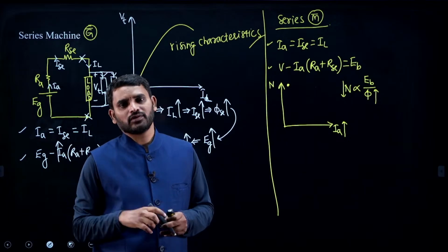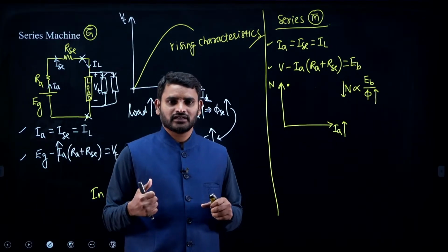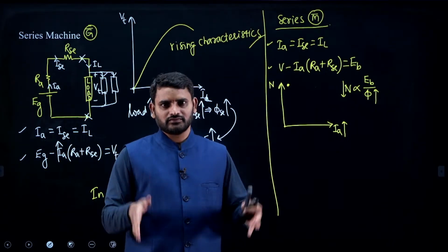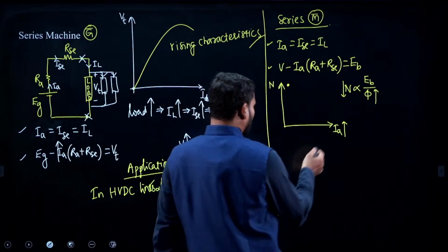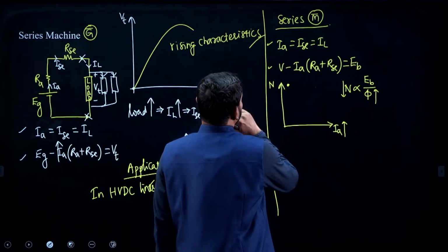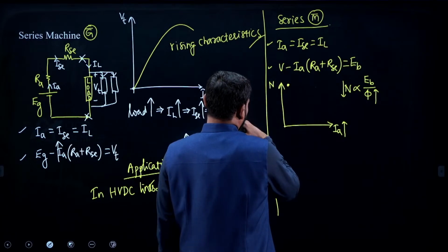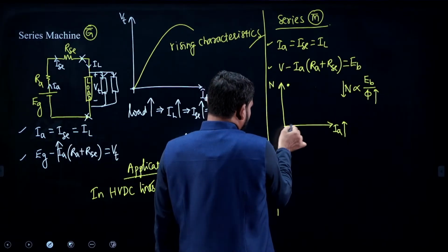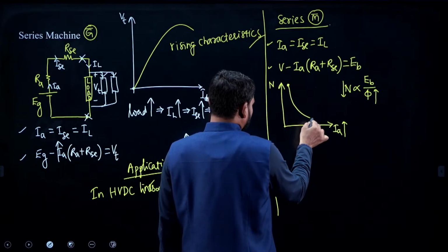We should put some load. That's why for trains, the bogies are the loads for the series motor. Always there should be a load on the series motor, right? Otherwise it will rotate at highly dangerous speed. Now whenever you increase the load, the speed falls quickly like this.